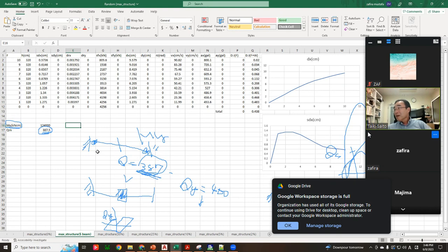Yes. So you want to combine metallic damper here. Because metallic damper has an upper limit, yielding by Qy. So it means viscous damper also cannot go over Qy.